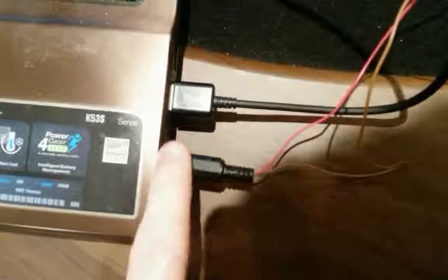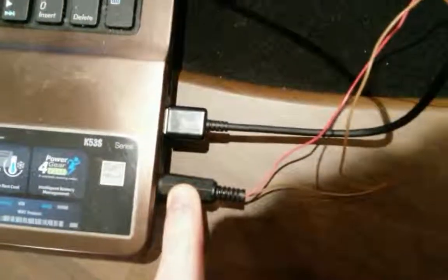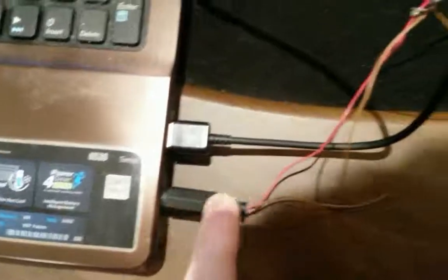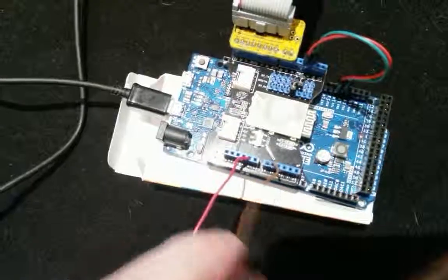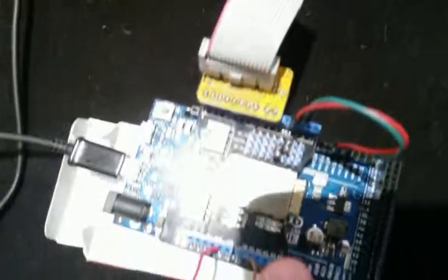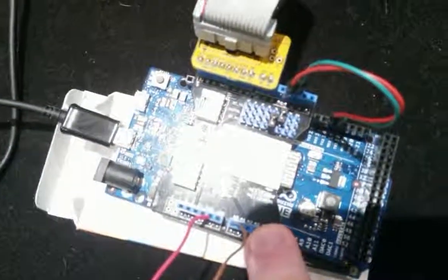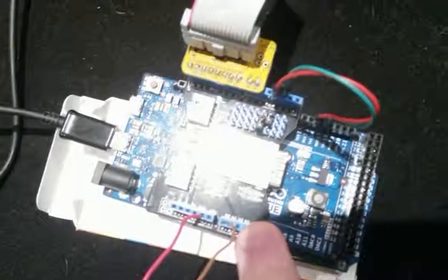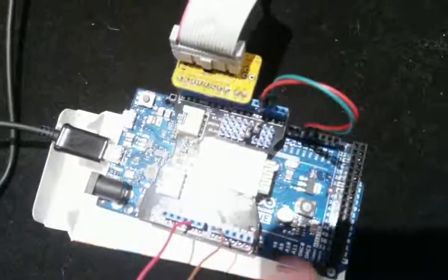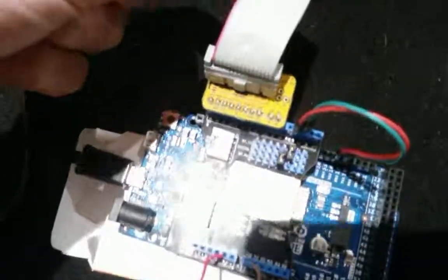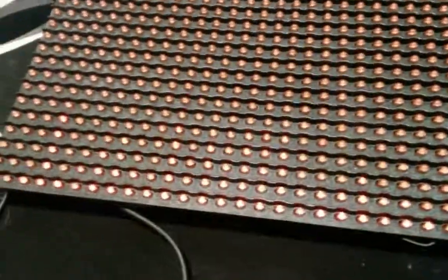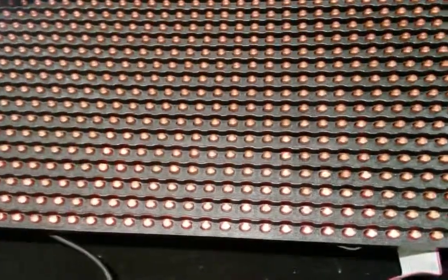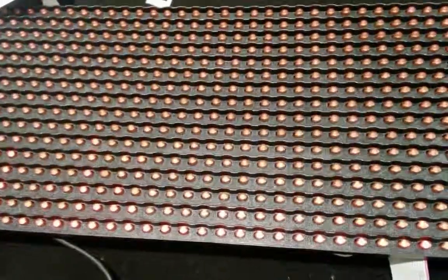And now for our feature presentation. As you can see, we simply take the audio output from the headphone jack of the laptop and input that directly into the analog input of the Arduino. The Bluetooth module here is simply allowing communication with the phone to turn on the LED matrix. Output from the digital pins of the Arduino goes into the matrix, which then displays the frequency information of the audio signal. I'll turn down the light so we can take a better look.